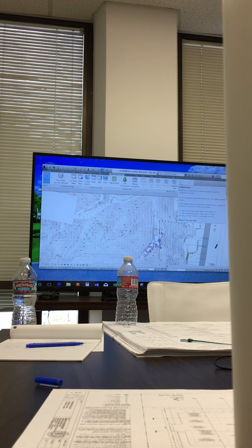Within Revit, you have the capability of phasing the project, such as with walls. If you did as-built drawings of a house, you would show all those walls as existing, not to be demolished, or you could indicate certain walls as to be demolished and the new construction phase.